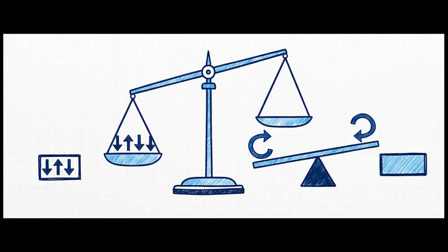And this brings us to the single most important idea in all of structural engineering. I'm serious. It's called equilibrium. For any structure to not fall down, it has to be perfectly balanced. And that means two things. First, all the forces pushing up have to exactly cancel out all the forces pushing down. And second, all the twisting forces trying to rotate it clockwise, engineers call these moments, have to exactly cancel out all the forces trying to rotate it counterclockwise. That's it. It's simple, it's elegant, and it is absolutely non-negotiable.